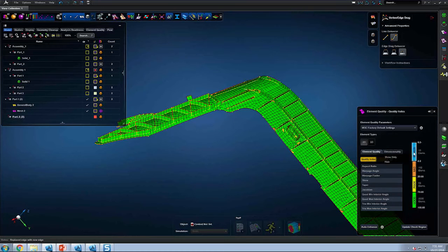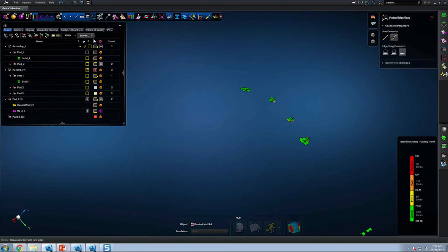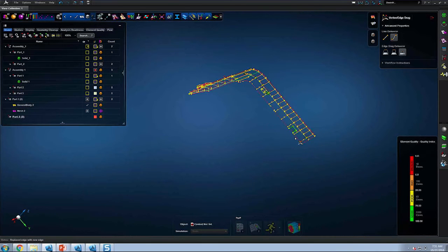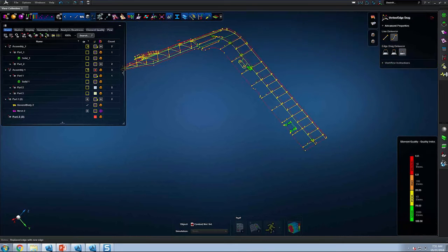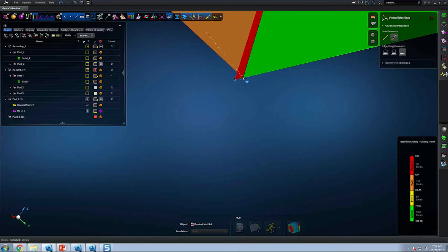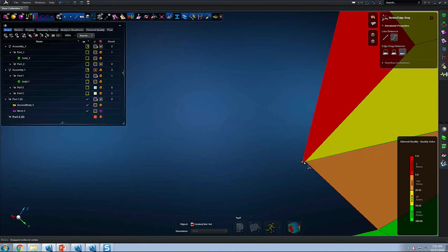And here, let's go ahead and look at our progress. And we'll grow the mesh, and this is reviewing regions of the model that still have a few issues that we can go ahead and rapidly fix in the model. Here, it's very subtle, but you see there's an overhanging vertex. And of course, when you see that here and there's a symmetric opposing end, there's most likely the same issue, so we'll go ahead and fix that.